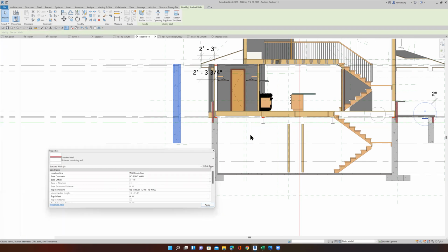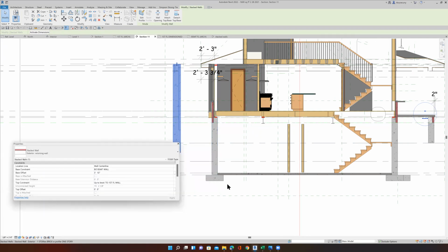Here, this is a house in Michigan, so the frost line is 42 inches. The floor of that, call it an areaway, will be 8 inches below the floor here. So the floor is going to be 4 inches below the bottom of that.